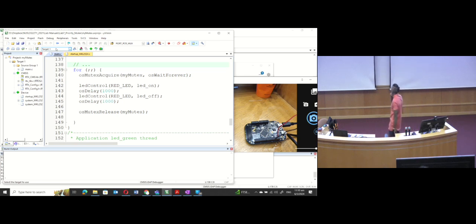Okay, so let's review the mutex and semaphore code so you understand some important concepts. For mutex, again you can go back to your website and go to the mutex link to understand the kernel calls. To create a mutex, we call osMutexNew. We need to first create a mutex ID type. The osMutexNew call is inside your main function here, where you create the mutex.